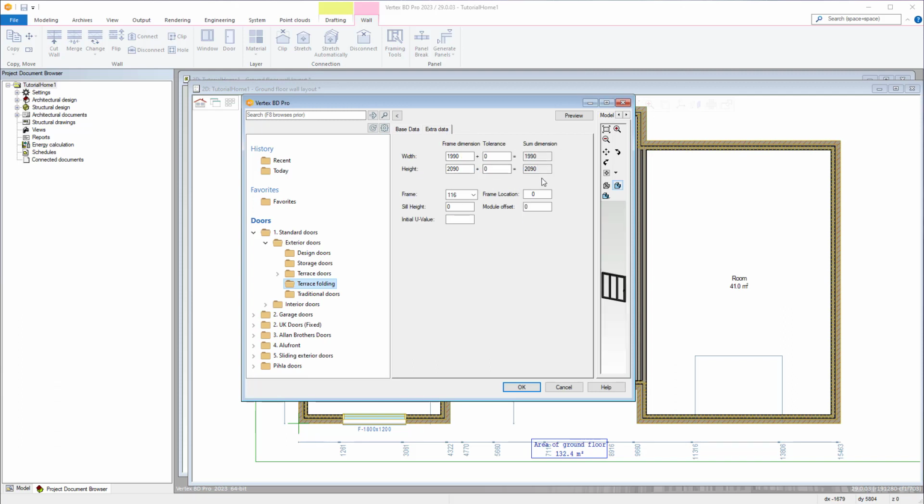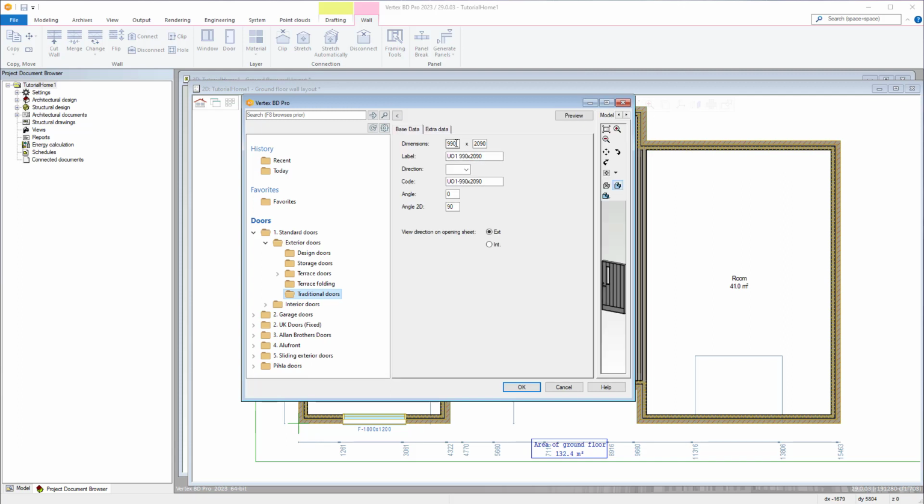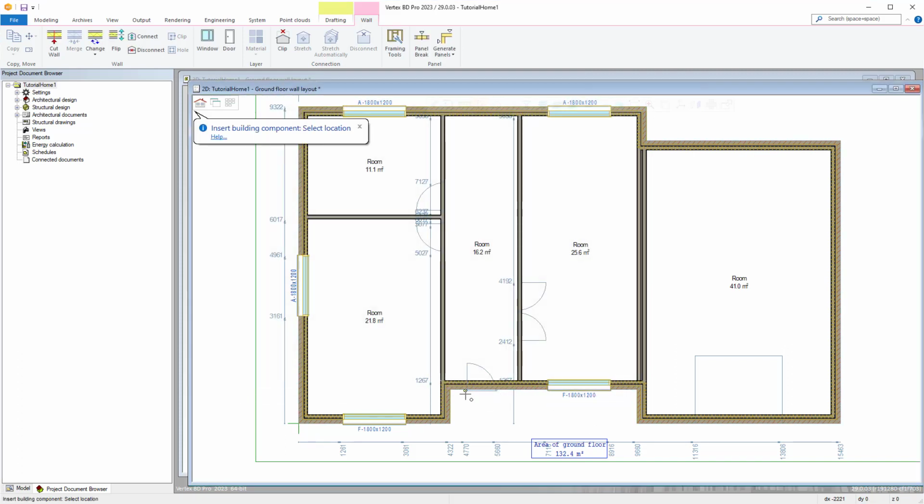Again, click OK and select the wall you would like to add the door to. The features as described when going through inserting windows also work here, however there are a few more features which might be of use, which include door leaf flipping and opening orientation options. Simply place the remaining openings in the same way as with the windows.